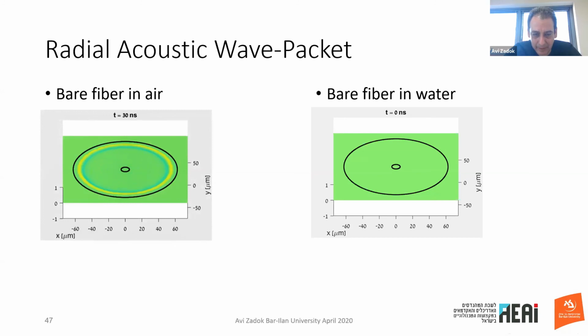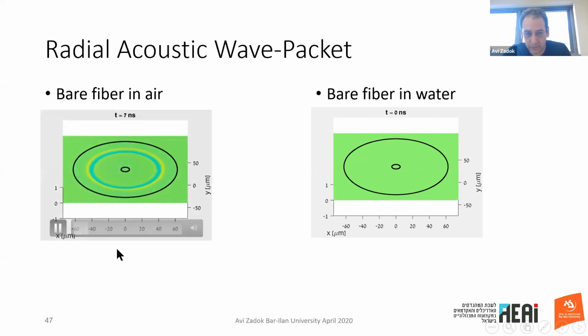It is stimulating a packet of these transverse acoustic modes that I showed you before, and this packet is propagating, I'm going to play it again, from the core outwards towards the edge of the cladding. And when it is hitting the cladding, like now, there is an elastic reflection. So every so many nanoseconds, 21 nanoseconds to be exact, the elastic disturbance is being reformed within the core.